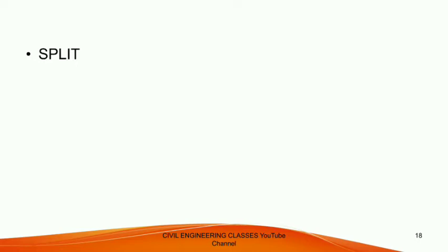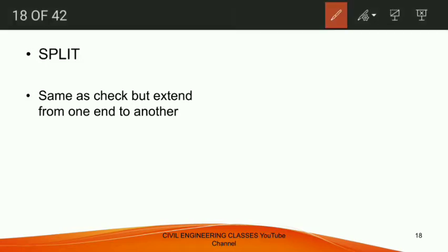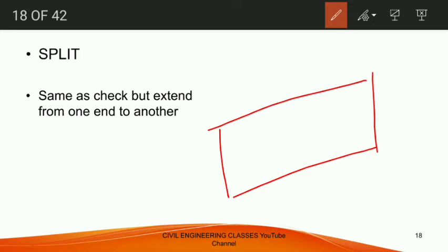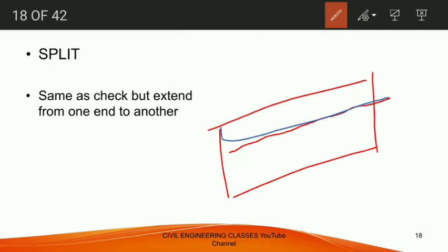Next one is split. Split is very similar to check, but it will extend from one end to another. If this is our wood section, if there is a cut that will extend over the whole section, this will separate the wood section into two. This is what is called a split.